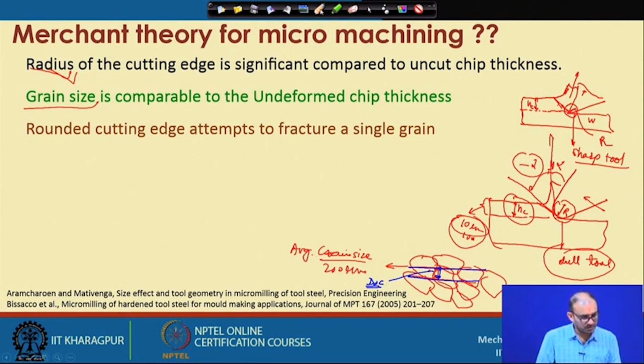So, here what is the problem? When you do machining at this particular scale, you sometimes have to cut the grain also, but that is not happening in this case because our uncut chip thickness is very large. It may be 0.5 millimeter, up to whatever is the capacity of the machine. You can even start with 100 micron, and go up to millimeters very easily in conventional machining.